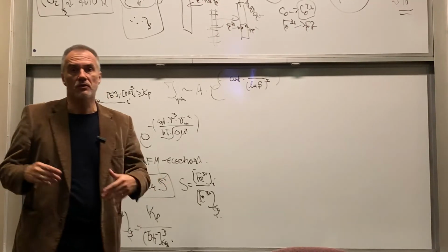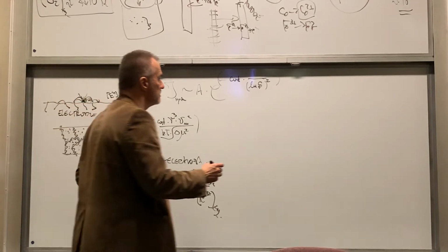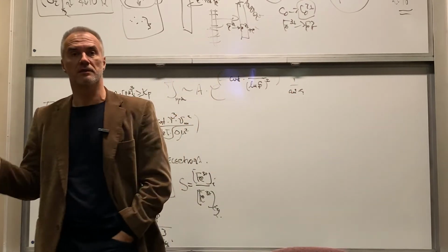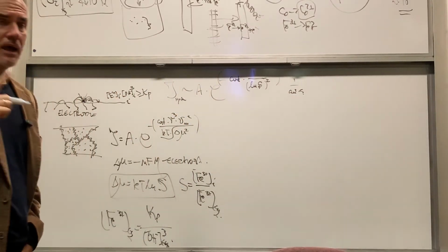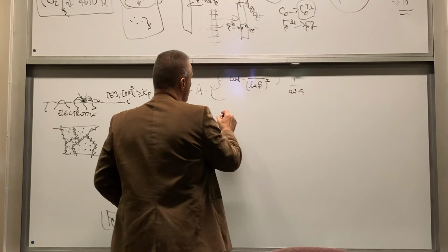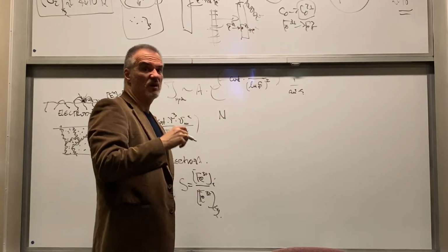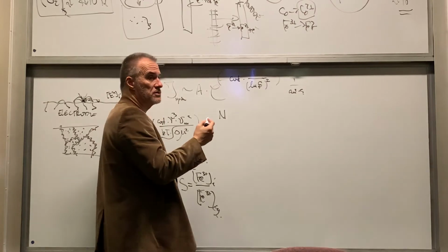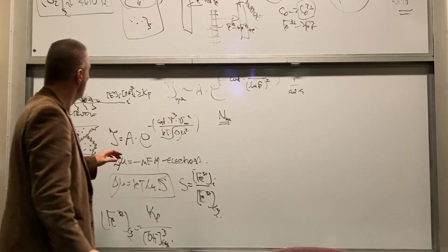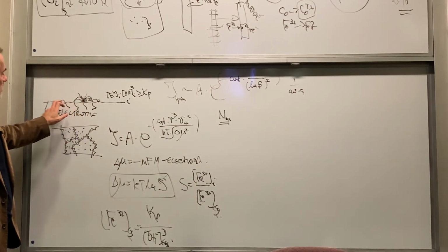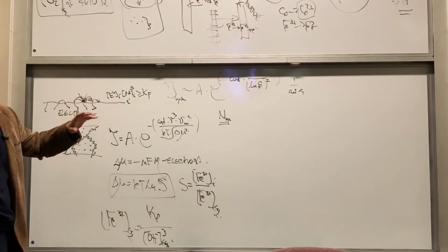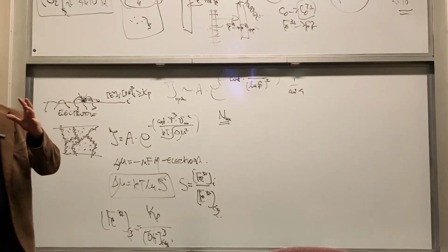Now, nucleation rate is, as I discussed with you guys, 1 over centimeter squared second, right? So number of nuclei per second per area. Now, if we assume that every one of these nuclei formed will grow to some size, proportional to some number of moles, before it gets buried, because I nucleate here, but due to the dynamics of the growth of the surface, they will eventually grow to a certain average size in terms of number of moles.